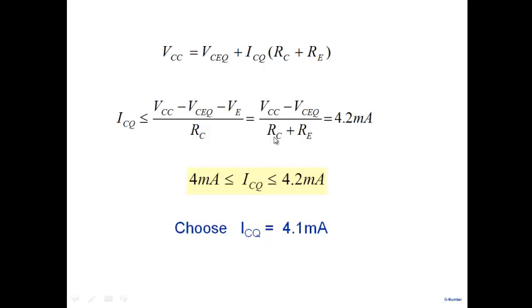The RC that you take, 2K, and if you go into the lab and you take 100 2K resistors and you measure their values, what will you get? You precisely measure the values. You will not get 2K. In some, you may get 1.9K. Somewhere, you may get 2.1K. You know that there's a tolerance. And if you want to make a really cheap amplifier, you use a very high value of tolerance resistor, let's say 10%. So it may go to 2.2K or it may go to 1.8K.